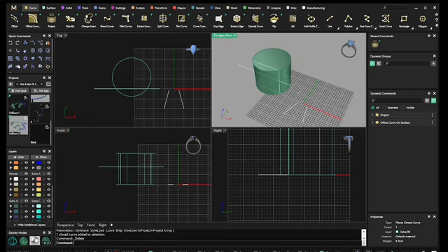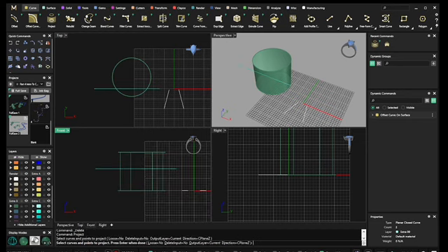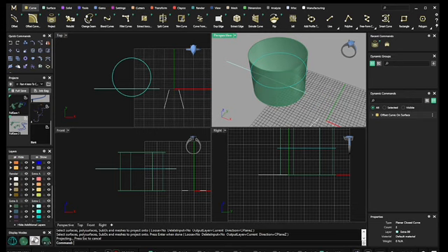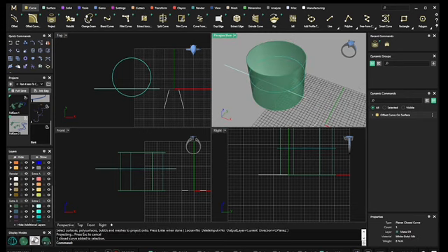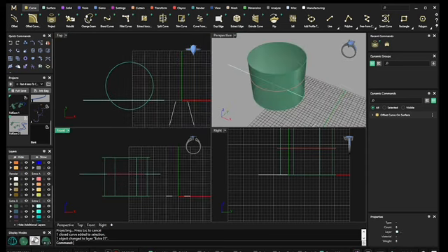So let me show you how I do it old school. All right. This is how I do it old school. Type in project, select project, select curves and points to project. I select this curve, I press enter when done. I select the surface and I press enter when done. And this is what I wanted the whole time. Now you can see my confusion why it wouldn't work. Let me put that on a different color. So let me just show you what happens when you go up in this viewport. All right, so I'm going to type project.